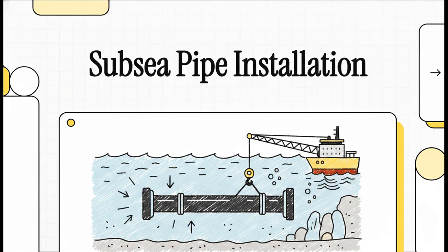Pick the wrong vessel method for your water depth, and you don't just get a slightly worse or slower installation, you get a pipe that buckles under its own bending stress before it ever even touches the seabed. Vessel selection isn't just some logistical scheduling decision, it's a fundamental, high-stakes structural one.